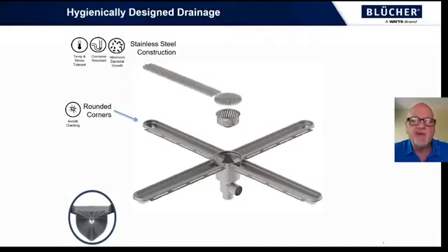It has rounded corners to reduce the risk of joint deterioration and cracks in surrounding floor finish. When you see cracking and failures around floor drains and trench drains, it normally starts at the corner on the 90-degree ends of the channels.